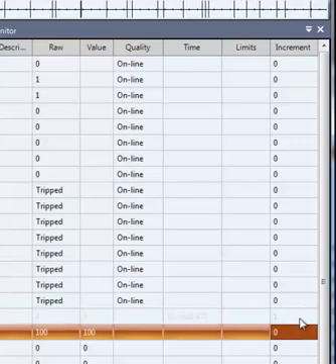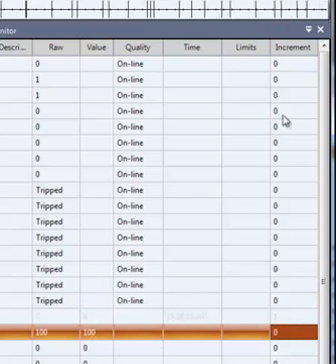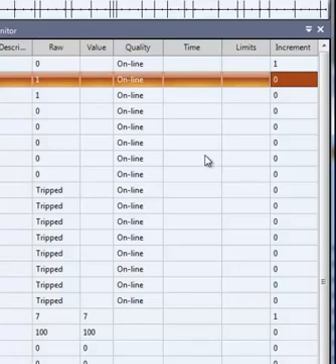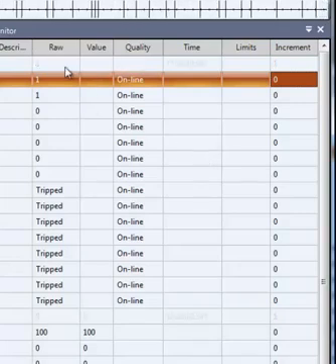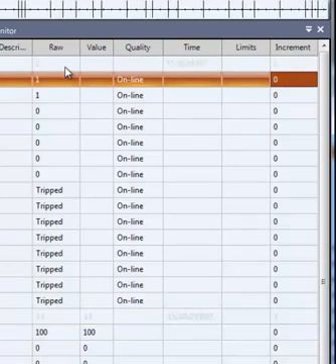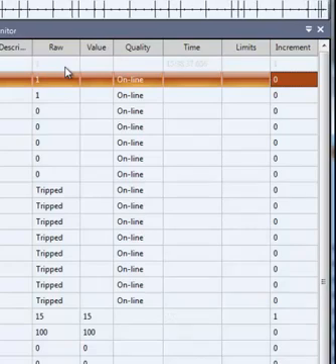For analog and pulse or counter points, the value is periodically added to the point's raw value. For binary or status points, an increment value of 1 causes the state to periodically toggle. For a 2-bit status point, the value can be 1, 2, or 3, and a new 2-bit state is periodically calculated by exclusive ORing the increment value against the last transmitted state to form a new state.